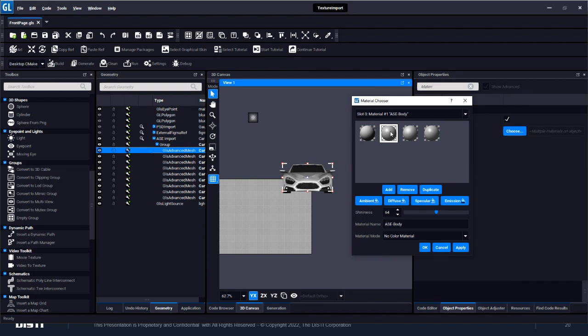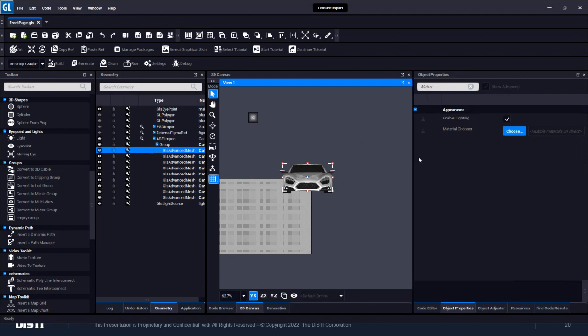So the body kind of encompasses the doors, and that encompasses the windows. So let's say I wanted to change specifically the color of a door because I've clicked on it or there's an animation playing on it or whatever you want to set up. Right now, if I were to change the material color of the body, it's going to affect everything that's referencing this specific material. So make sure that if you are going to be doing something like that, each of those does have a unique ID material on them. So when you change it, it just changes for that specific object.